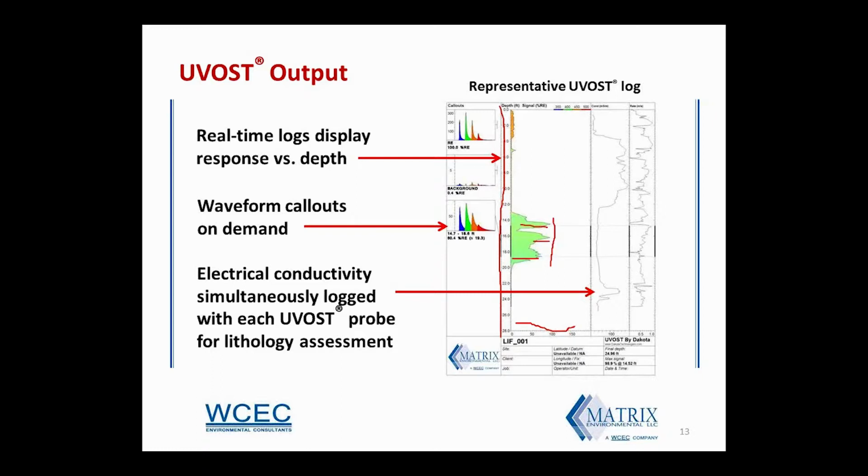So before each new boring, a reference emitter, known as RE, which is essentially a calibration standard, is placed directly on the window of the instrument to set calibration. And the RE contains a mixture of fuels including gasoline, diesel, kerosene, and other oils. And then that calibration waveform is put on each log right here.